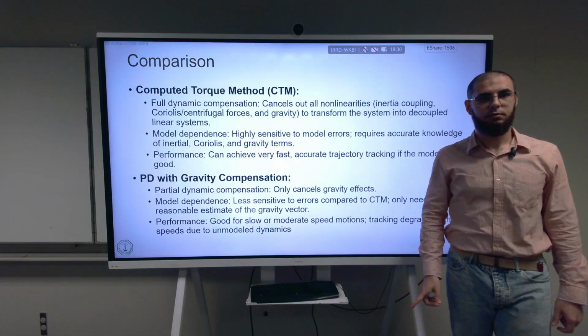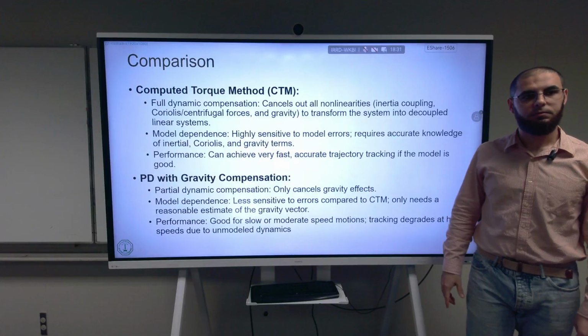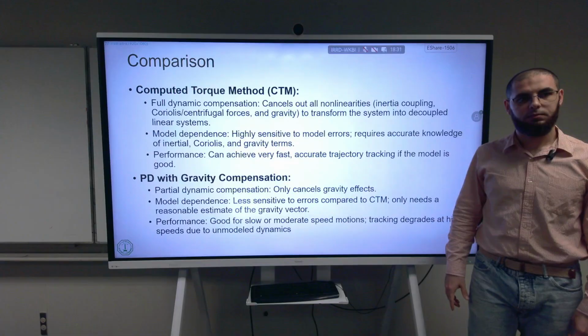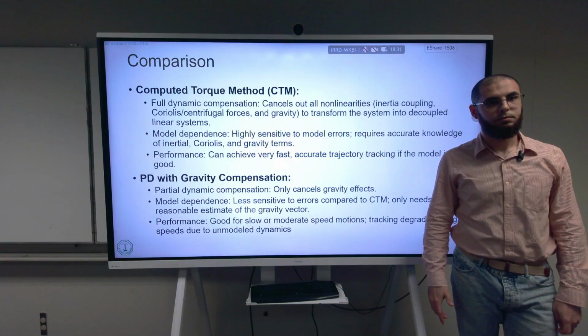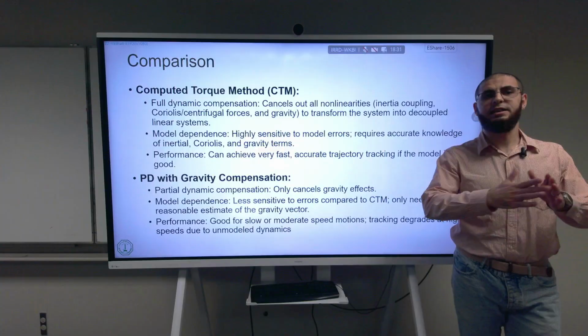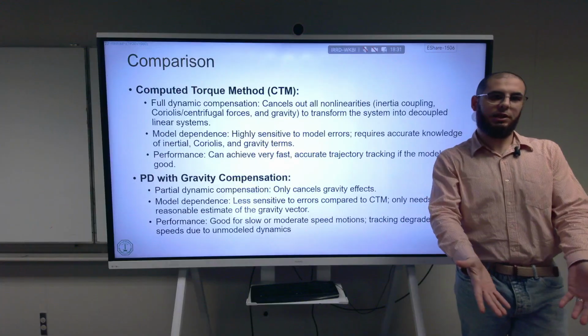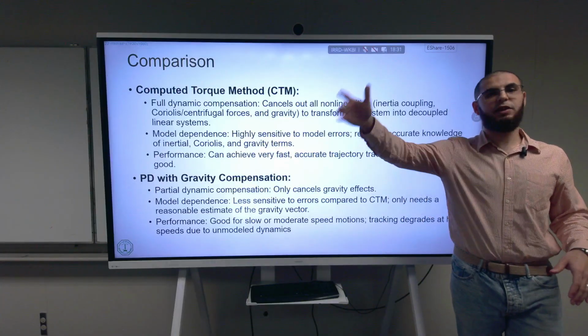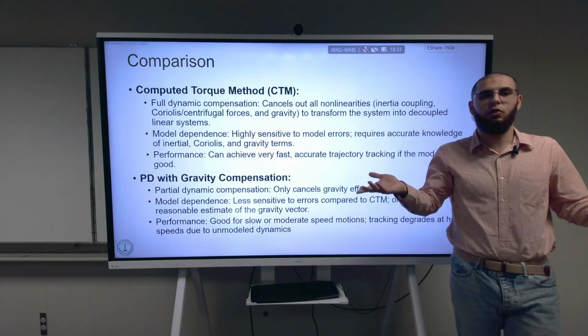Yes, right. The computed torque method, does that mean that people have to remodel the system after a while? For example, if the system got worn down or there's a problem with the power electronics, does that mean that every time they run the system they have to remodel? Wearing is usually at a very low scale compared to actually knowing the dynamics right now. So if it's every month and every year, this is not the problem we're talking about.